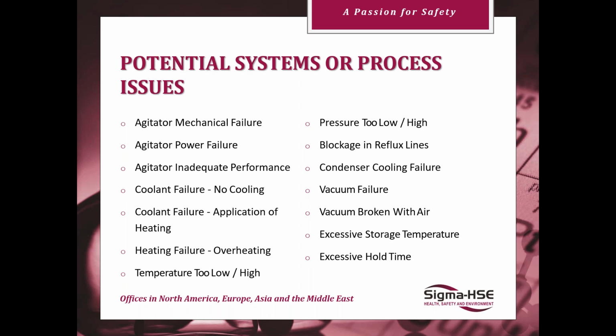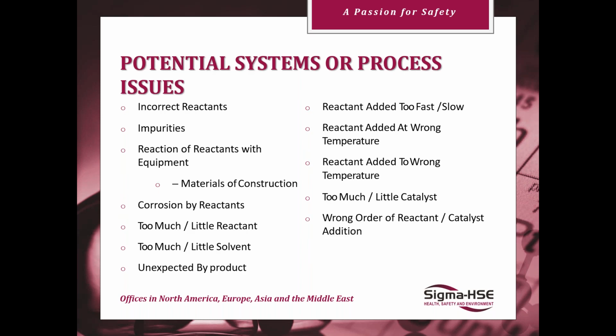That kind of non-homogeneous system can lend itself to spot heating, which can cause an issue. On the flip side of that, coolant failure, heating failures with overheating, like the steam example, temperature, pressure, blockages, which will increase the pressure in the reflux line especially, condenser, vacuum, storage, all of these are many reasons that might cause a runaway.